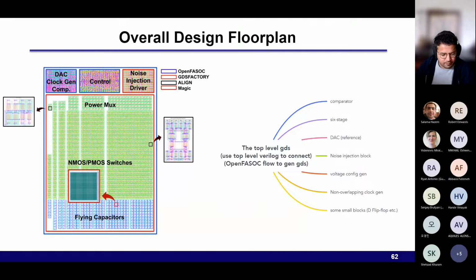Okay, I see. Do you have a better way to do this? Oh, no, I'm mainly just asking, but maybe it's something like annotated GDS or something like that. Yeah, I mean, GDS with SPICE is a good way to do this, but OpenROAD doesn't understand the GDS. There's no GDS to DEF parser. Yeah, I think there is one in Magic, but I've never tried it.